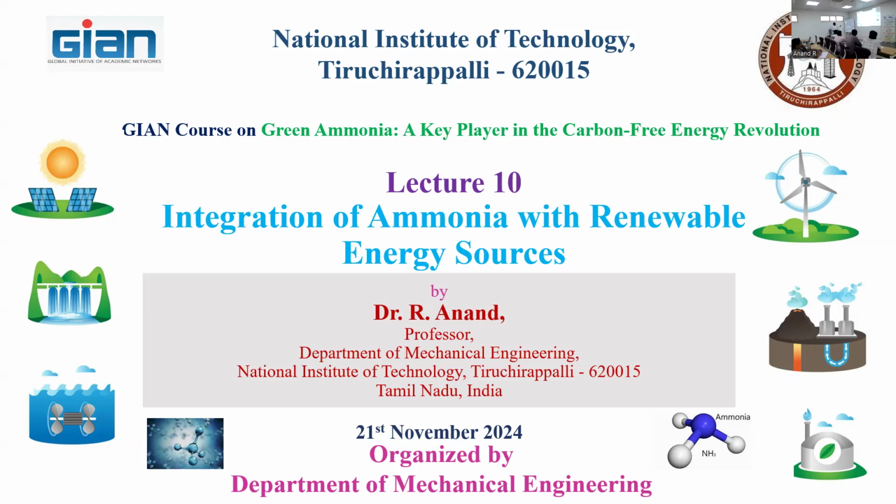In the same way, you collect the solar radiation and focus it at some point. It's called a concentrated solar collector, where at the concentrated point you have the boiler. The CSP, concentrated solar power plant, is similar, where all the heliostat mirrors are placed on the ground. All radiation falling on the mirrors is focused at one point. Concentrated at one point is called CSP.